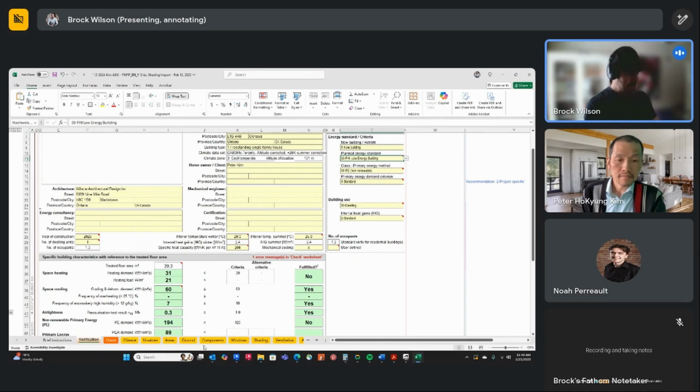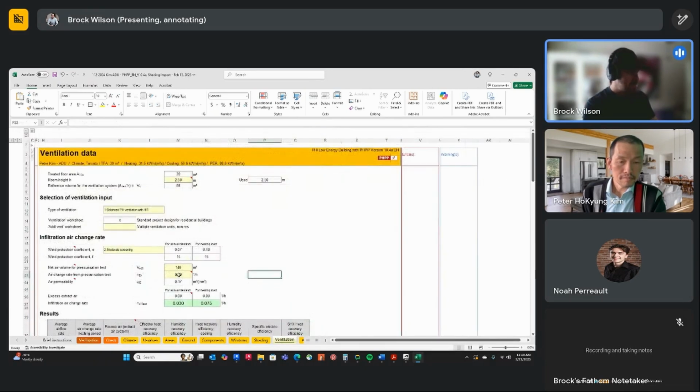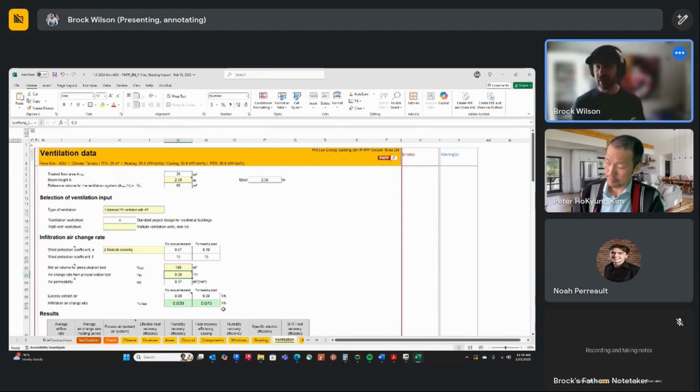We can play with this as well. As you know, there's massaging back and forth. I'll probably say massaging a couple times. That being said, we have an air change rate of 0.3 air changes per hour, which I think is quite achievable. One of our clients achieved a 0.3 ACH in their 1,800 square foot home, and they did all the work themselves.